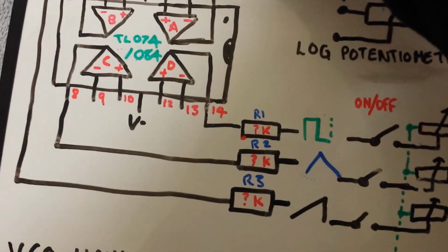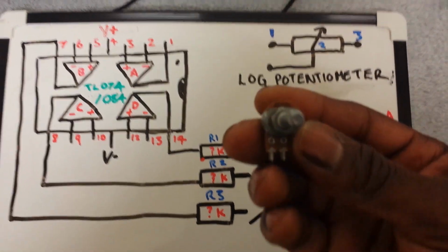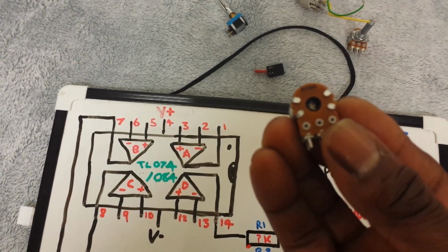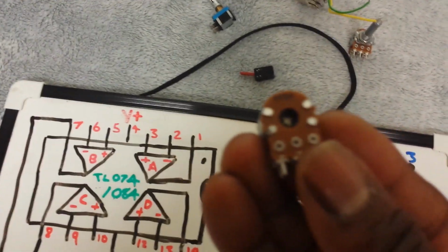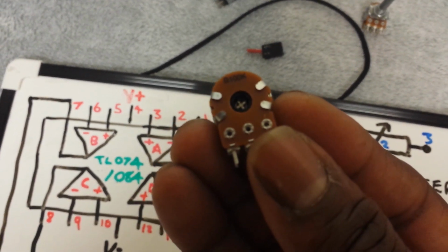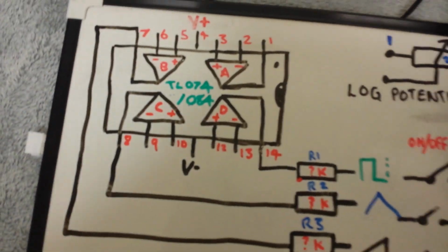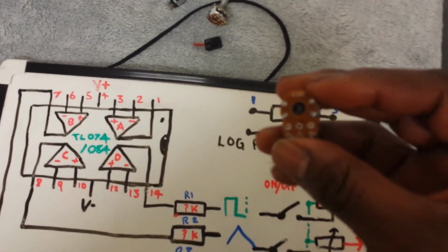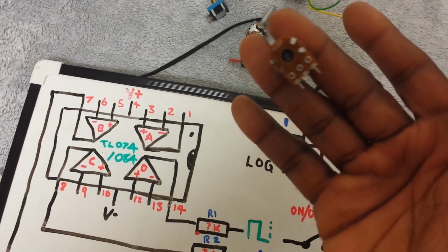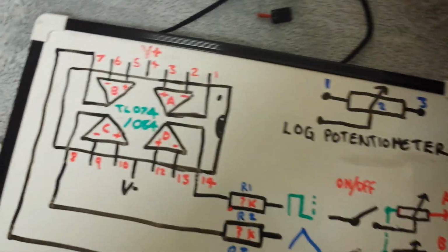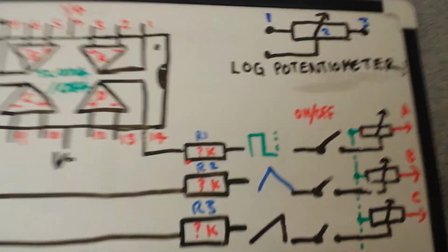If we look here, we have our potentiometer, and another thing I need to mention is that, if possible, it's probably best to go for a certain type. This is a B type, if we can see that. The camera can't quite focus. That's a B type, which will give us a linear response. Now the human ear has an exponential response to volume change, hence we use these A type, which are the logarithmic potentiometers. Right, let's get this the right way around.